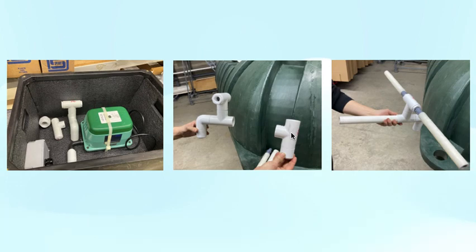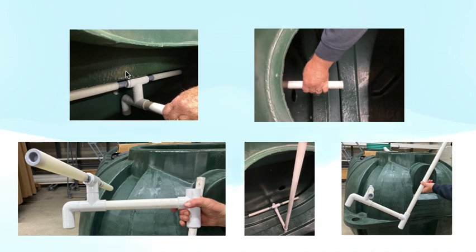So once you thread in your diffusers, what you're looking at here, going from left to right, top to bottom, you'll notice that this wall where my cursor is circling, that's the partition, the wall in between separating the two compartments of the tank. You'll see that the pre-manufactured piece has this cap below here to keep the diffusers off the bottom of the tank, but it's also keeping the diffusers a little bit separated from the tank as well. So you can see just below here, this area is going to be resting on the bottom of the tank, forcing the diffusers to be above the bottom so it's not just blowing into sludge.